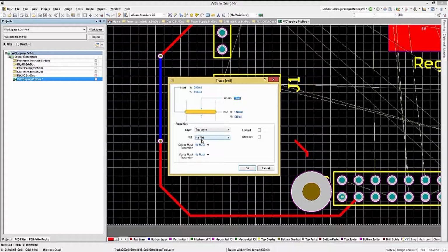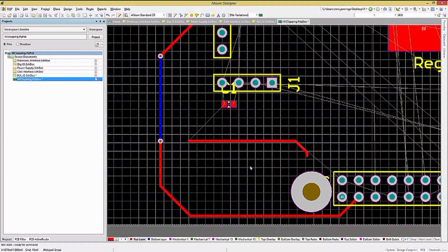While it is faster to start on an object in the PCB with a net name assigned, if you have a track already laid down that has the no net assignment, simply double-click on the track and use the net pull-down menu to select the right net. If you start to type the net name, typing G, this would cause the menu to jump down in the list of names, speeding up the selection process. Now we have assigned the ground net name to this track.